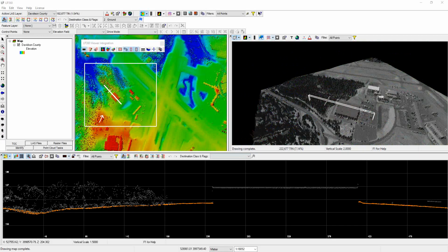Okay. Yeah. So, one question about the display. I mentioned for the map view, you're going to get a certain level of decimation that's shown here. That same decimation level will be applied to the 3D view. Should you ever want to force 100% view, so this is what someone's asking, can you make sure that you're looking at all of the data? There is a toggle here which basically says go ahead and, what's my tooltip? There we go, force 100% resolution.